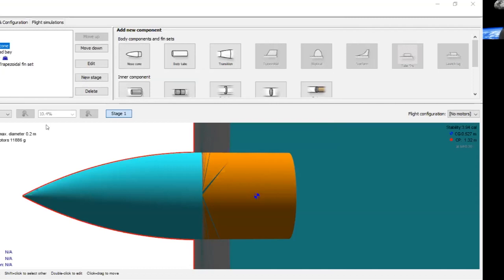If you were to take this design here, lay it out on a piece of cardboard, and cut it out so you've got a flat model, and then tie a piece of string to that and balance it, the point at which it would balance would be the centre of pressure. So it takes into account all these extra dimensions, all these extra bits here. Effectively the area times distance of all of these bits behind that point is the same as it is in front of that point.